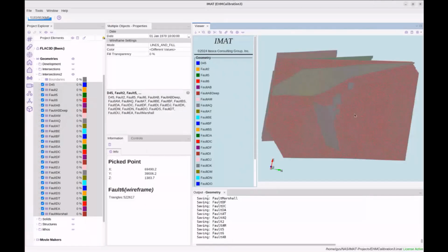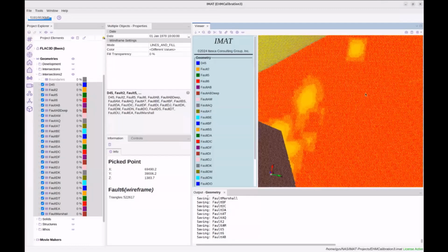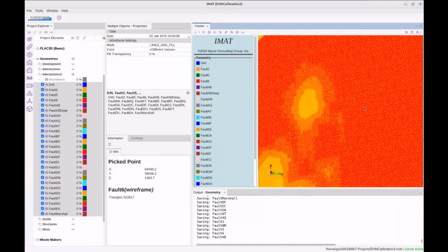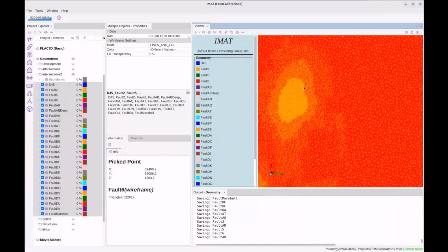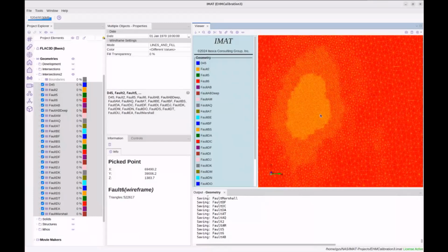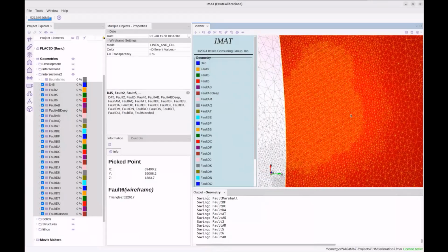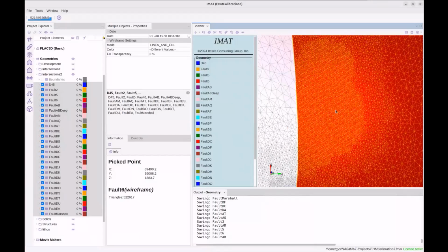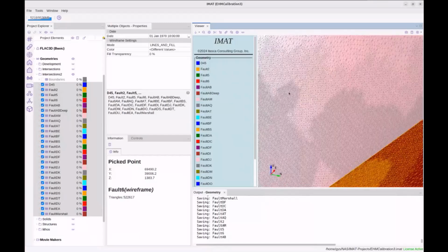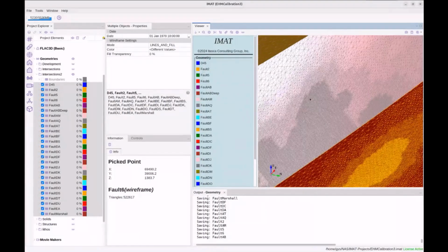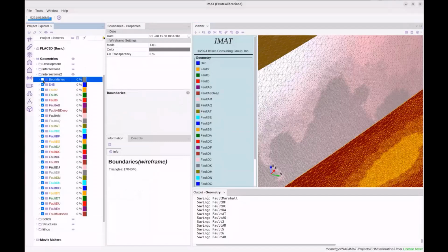This red structure, we started off with an octree grid with coarse cell size, and as it cut the octree mesh, where we had areas of fine refinement, you can actually see the sizes of the triangles on the surface becoming smaller. So effectively, what we've got now is a mesh that can be cut directly into an existing Flat 3D grid that's finer.